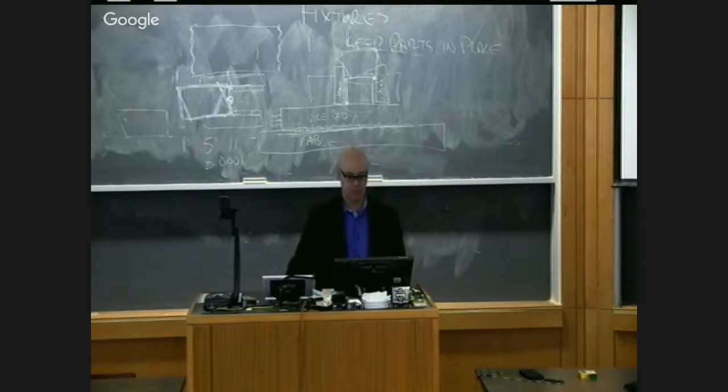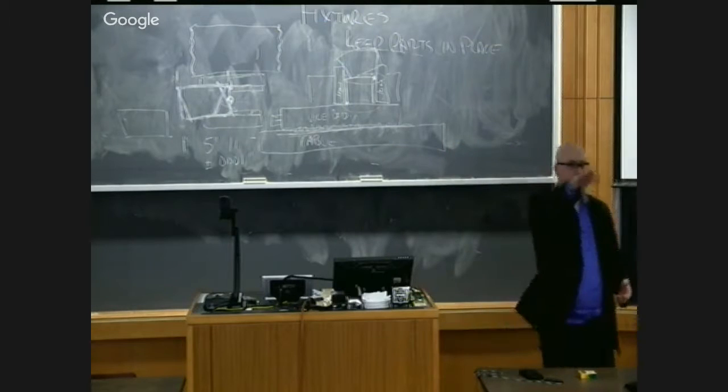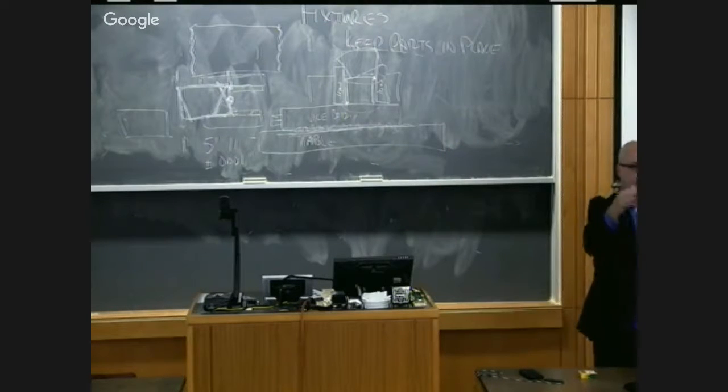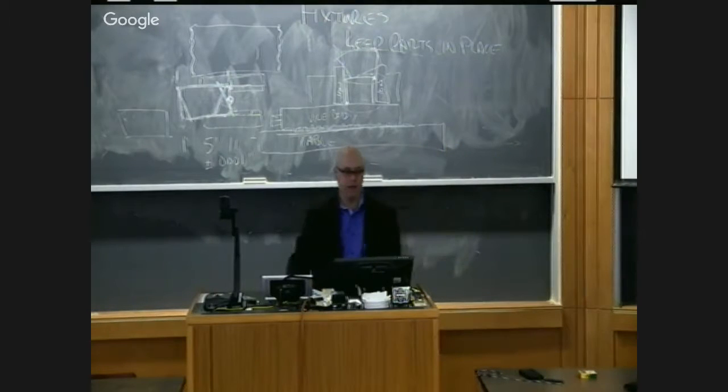Is that what a drill mill is? So the drill mill is in fact an end mill that's intended to cut in the Z direction. Okay. So what's the physics of the chip formation as we look at the cross section, the bottom face of the end mill? So what causes the cutting again?